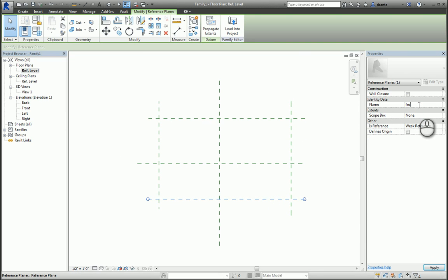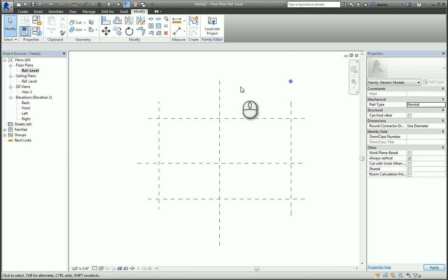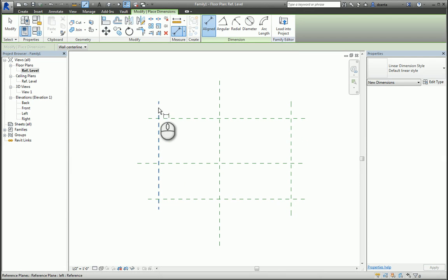Now, when we're working with the software and building families, you want to make sure you also take into consideration how this thing grows and adapts and changes. What I mean by this is that if the table that I'm building increases in width or depth, do we want it to grow equally or unequally from the insertion point? Most of the time, we want them to grow equally. So we want to make sure that we set these rules up properly so that they get built properly.